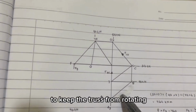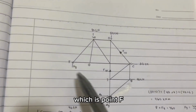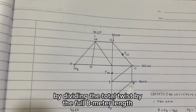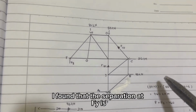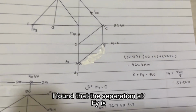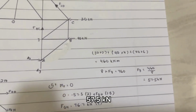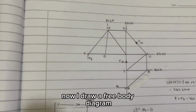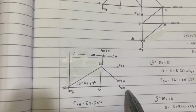To keep the truss from rotating, the upward force at the right end, which is point F, must balance this out. By dividing the total moment by the full 8 meter length, I found that the support reaction at Fy is 57.5 kilonewton. Now, I draw a free body diagram of the right hand section.